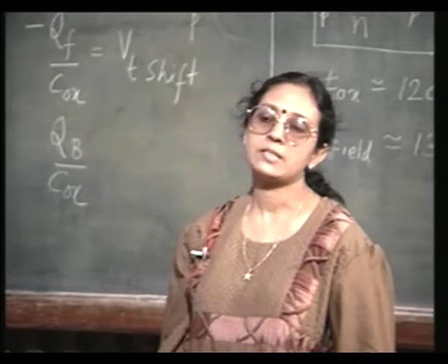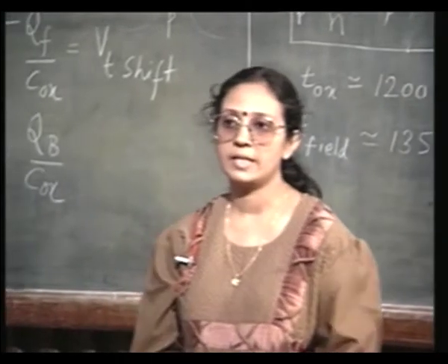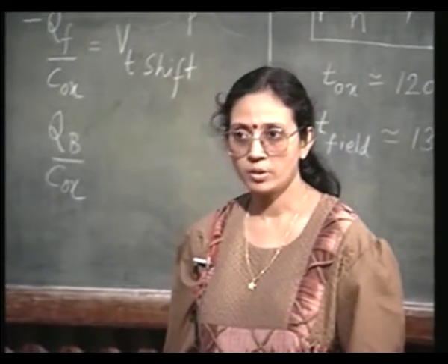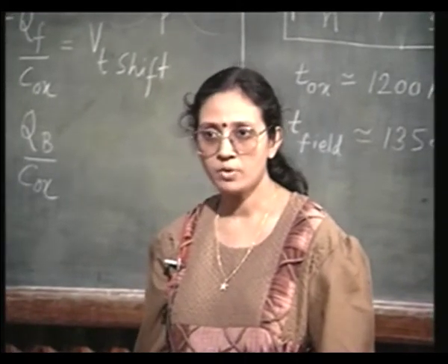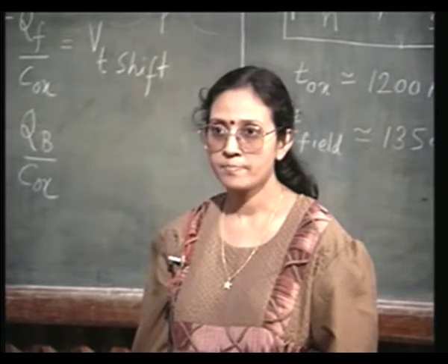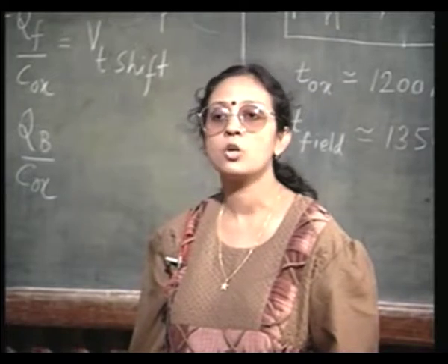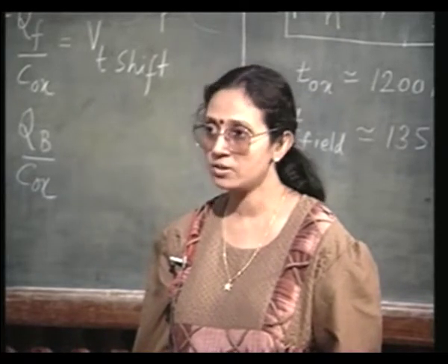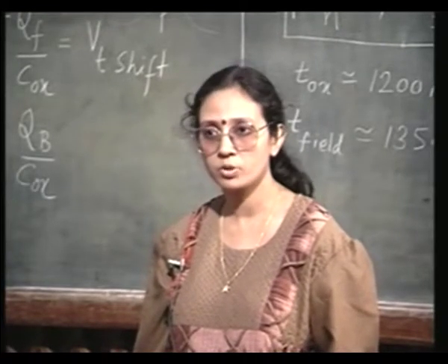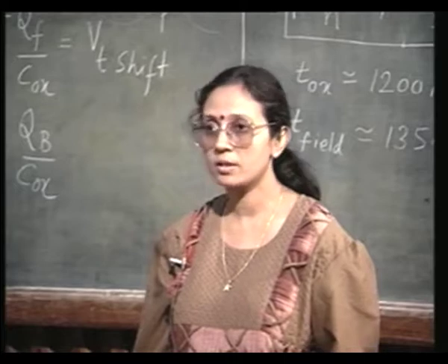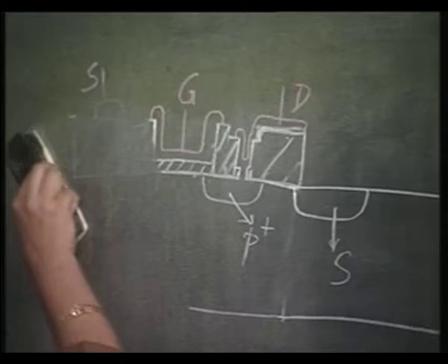One way to achieve this is if we first define the gate region. Okay. So, we have thick field oxide everywhere, we open an active area, then we define the gate region. So, whatever is not protected either by the gate or by the thick field oxide is subjected to source and drain diffusion. So, automatically source and drain gets aligned to the gate. Do you understand what I am trying to say? Suppose I have a scheme like this.